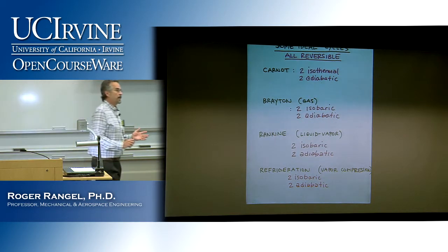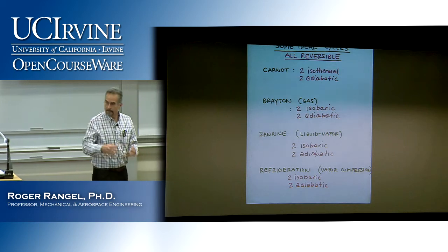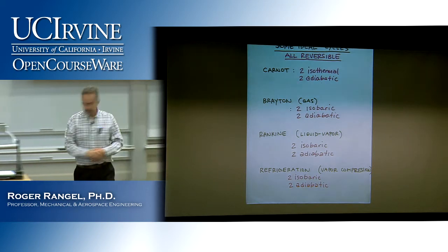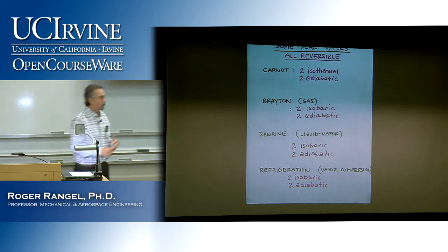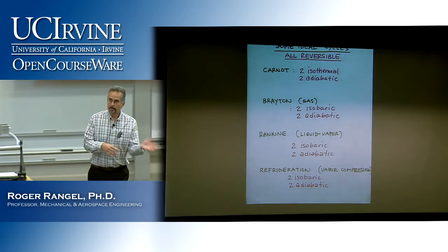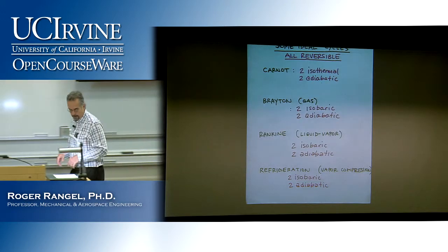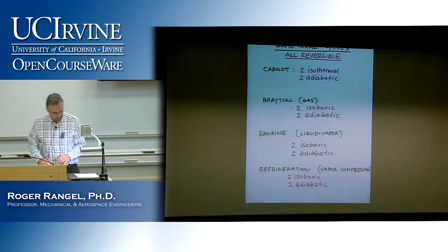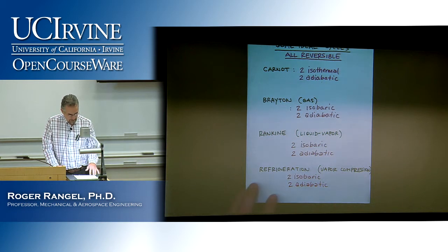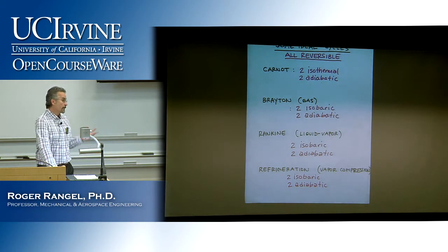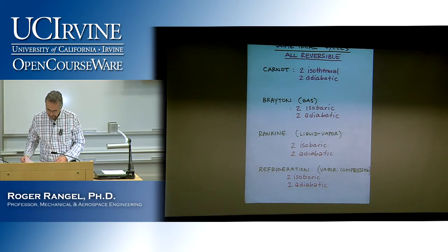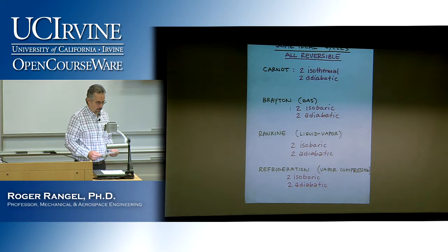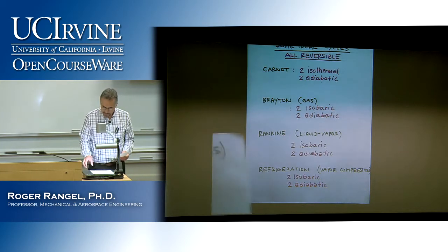It's the cycle that you see in a power plant that is producing electricity. It operates normally on a Rankine cycle with steam, water, as the working fluid, going liquid to vapor, back to liquid, and so on. So the Brayton cycle uses gas, typically air or a mixture of air and fuel, and the Rankine cycle is a liquid vapor cycle. And I also wanted to show you what they look like on property diagrams. For example, if we look at a Brayton cycle,